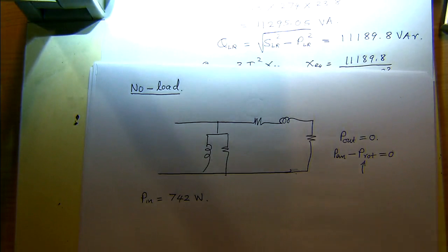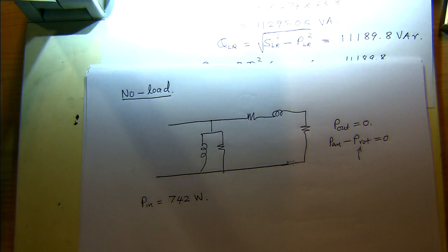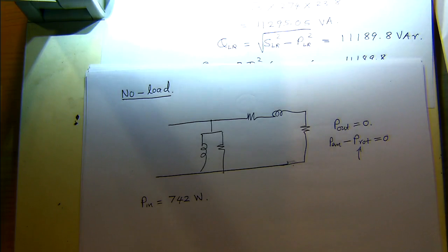So it says we can scale it linearly with speed. Although it's 300 watt at 2940, if you were to scale it linearly with speed at 3000 RPM, so when it's running under no load, the speed is really close to 3000. Maybe it might be 2999 or something like that.